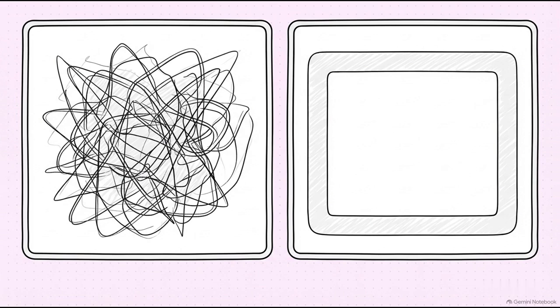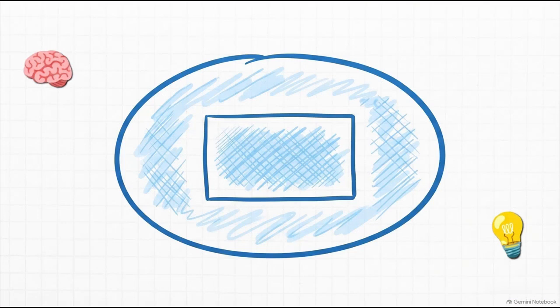A network is simply an interconnection of electrical elements. Period. It doesn't even need a closed path. But a circuit? A circuit is generally a network that actually contains at least one closed path where current can flow. So the crucial point to remember is this easy rule of thumb. Every circuit can be viewed as a network, but not every network is necessarily a circuit. Imagine 2 resistors connected in a straight line, but not looping back to a source. You've got a network, sure, but you don't have a circuit.